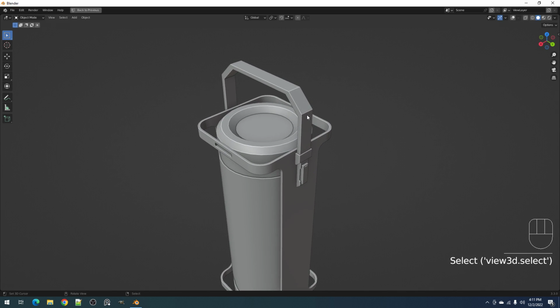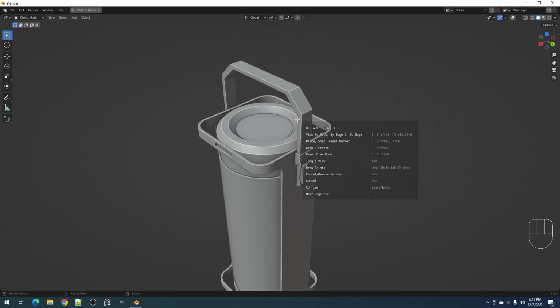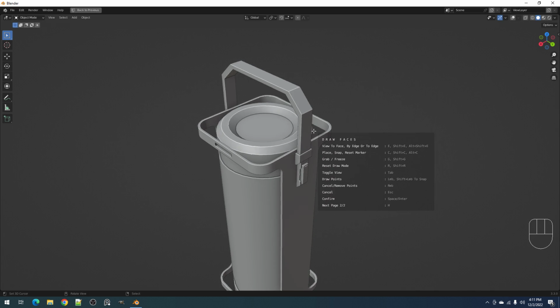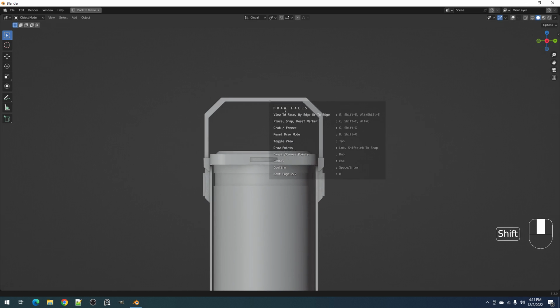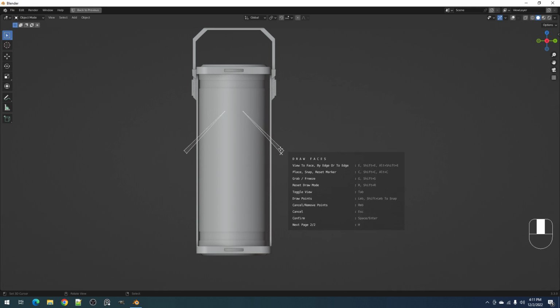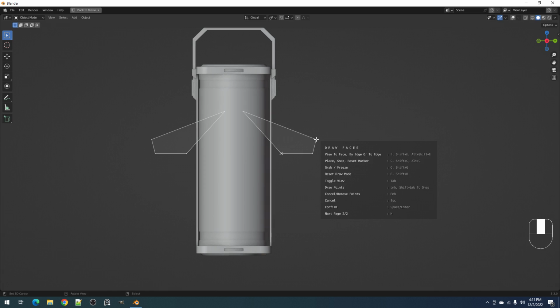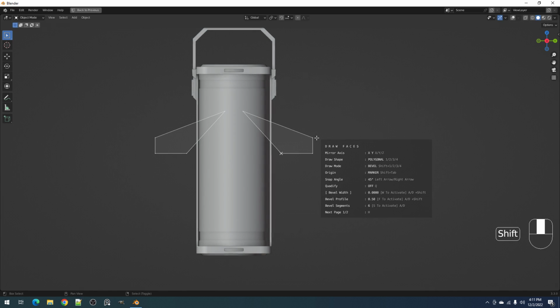So snapping works with, we have the controls, draw points, shift plus left mouse button to snap. That works for polygonal and strips. So polygonal, when you're drawing, press shift to snap it to the snap angle, which you can change the value of using the left and right arrow keys.